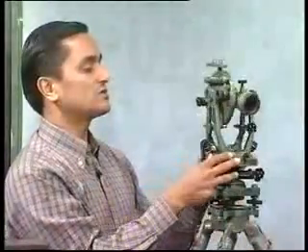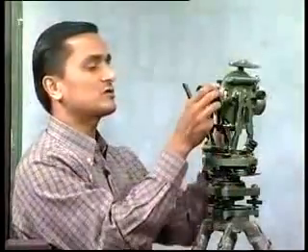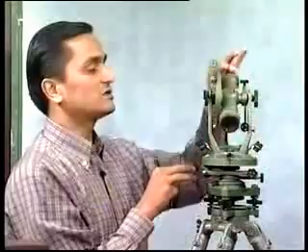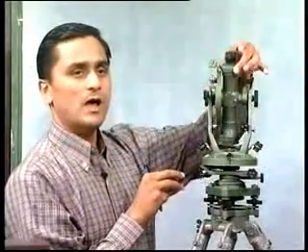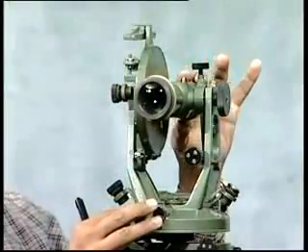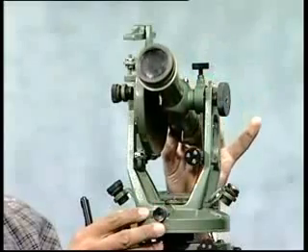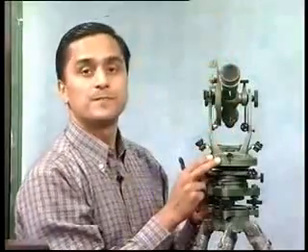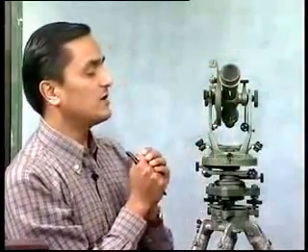Furthermore, there are more interesting things here. We'll talk about the telescope later on. Well, what I can do here, I can rotate this telescope. As we have seen, while measuring the angle, particularly the vertical angle, we need to sight some object, for example, like this. And this should give me the amount of the vertical angle for a particular point here. So how do we observe that vertical angle?